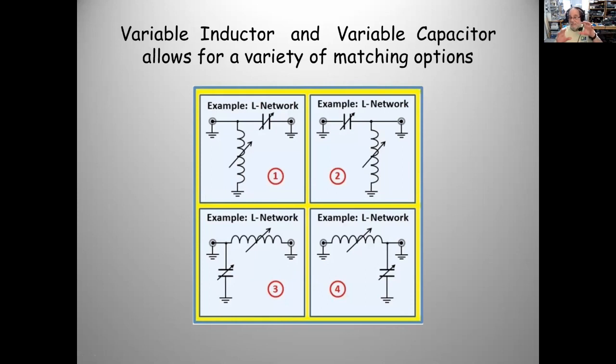With my Nano VNA, I put it at the input of the tuner, then the tuner to the antenna. When I'm looking at the Nano VNA, I turn the dials on the tuner until, looking at the Smith chart, where's the cursor? In the bullseye. It's easy to do. How much power am I using in my Nano VNA to tune up my antenna? About a milliwatt. Am I going to QRM some net? No. I could use my radio, but then what often happens is I set my radio to 5 or 10 watts, I tune up on the net frequency, and everyone else is yelling, "You lid, move off the net frequency." It always happens.